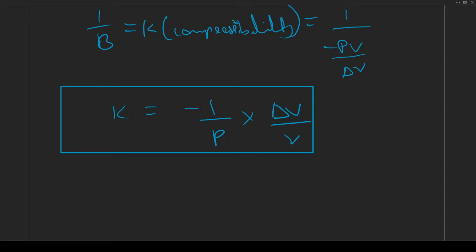The pressure exerted by a 3000 meter, 3 kilometer column of water on the bottom layer, with the formula pressure P equals h rho g, equals 3000 into 1000, the density of water, into 10 meter per second square, which equals 3 into 10 power 7 kg per meter second square. That is the pressure: 3 into 10 power 7 Newton per meter square.